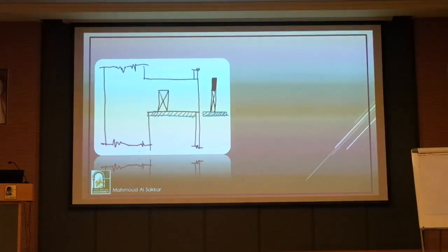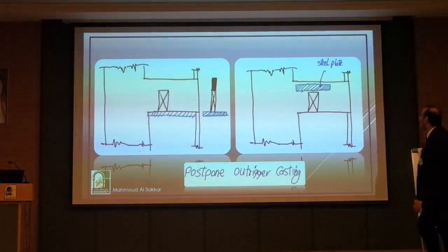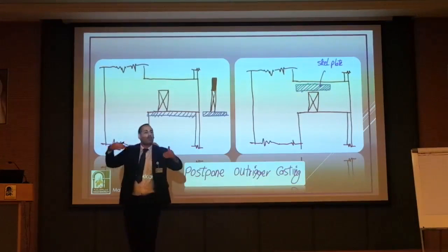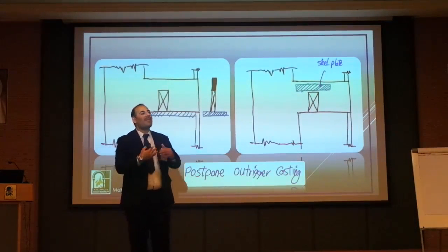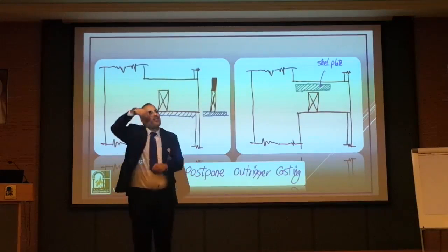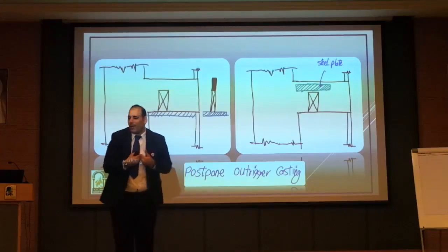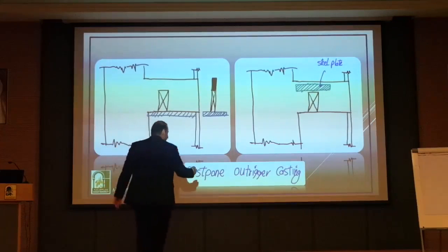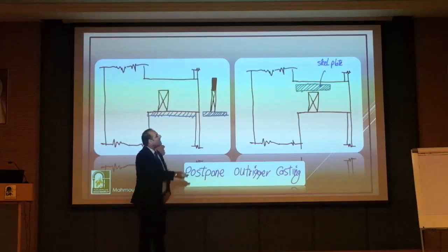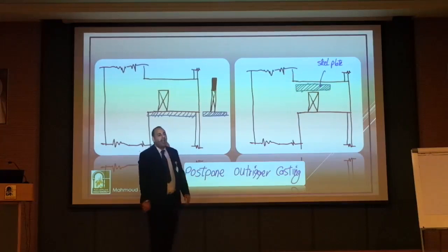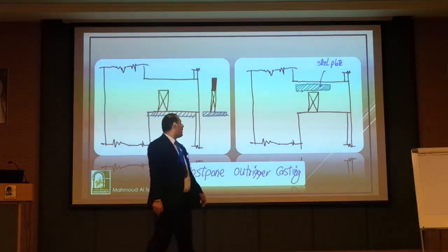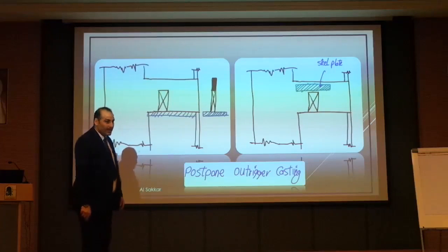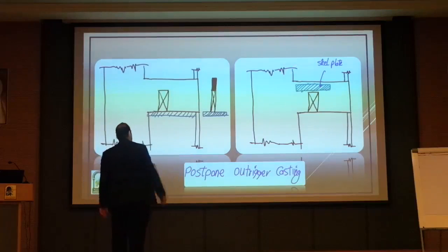But I still have a problem in shear. So at the moment, shear is still a problem. Yes, I can do something: I can use something called a steel plate. A steel plate is not going to carry compression from the shear. The shear makes a tension diagonal and a compression diagonal. For the tension diagonal, I can add as much reinforcement as I can, but the compression diagonal is going to make a problem in concrete. But steel doesn't have the same problem. We can use a steel plate here. Or, as has been done in Kingdom Tower, the one which is going to be the tallest in Jeddah, they use what is called the strut-and-tie method. Strut and tie is going to solve the shear problem.